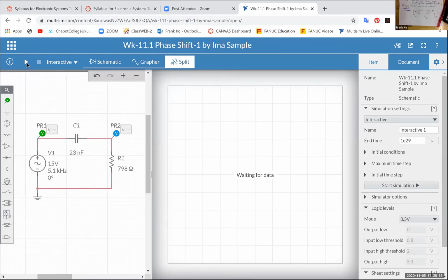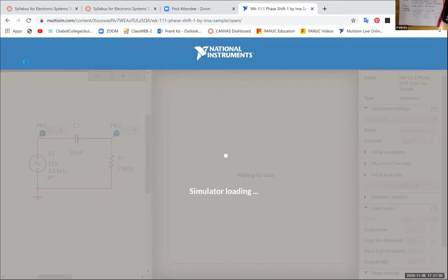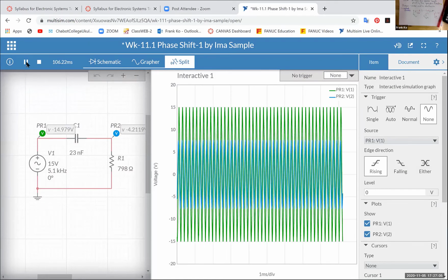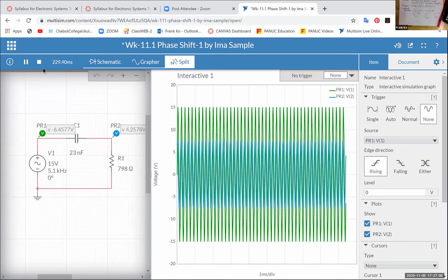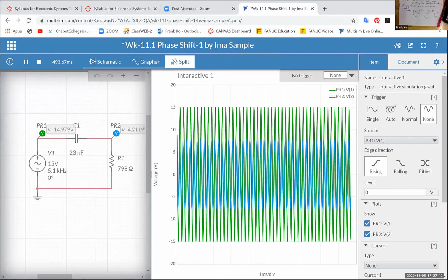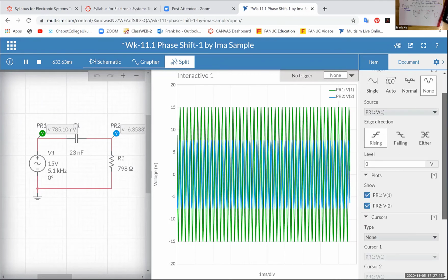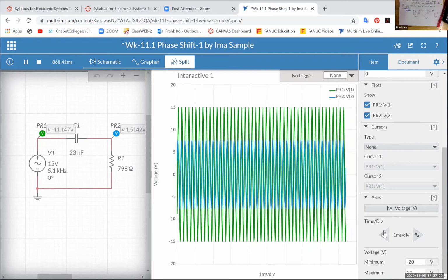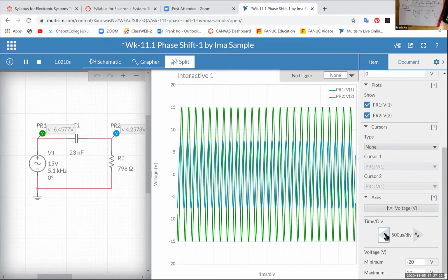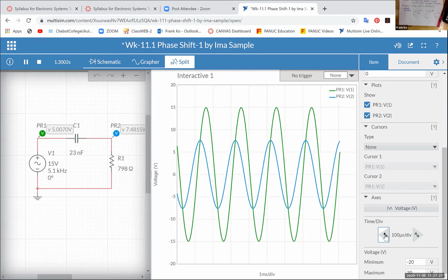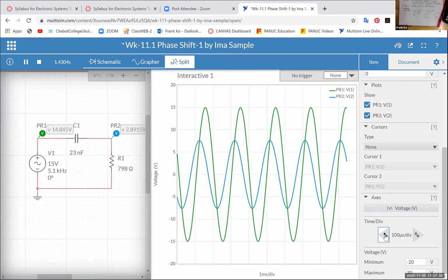So the play is right here. This is your go button, your play button. Boom. And while it's running, ooh, look at all those waveforms. Too many waveforms for us to look at and read, not a problem. We keep the dialog box open. We bring the scroll bar down. And by bringing the scroll bar down, you have the ability to play with time per division. I'm going to click here once, twice, one more time, 3 times. Now I've reduced the number of waveforms on my display.